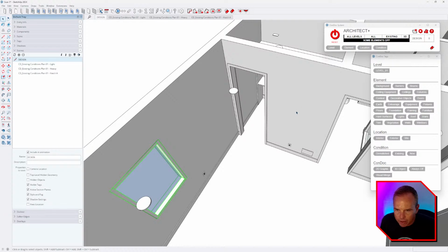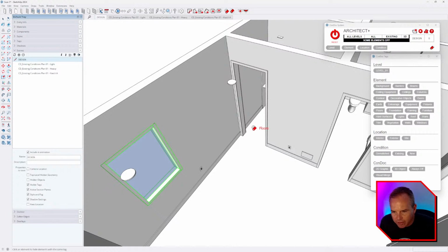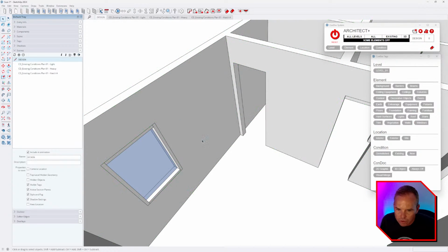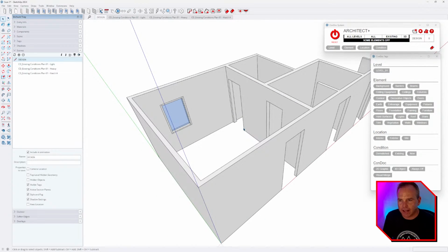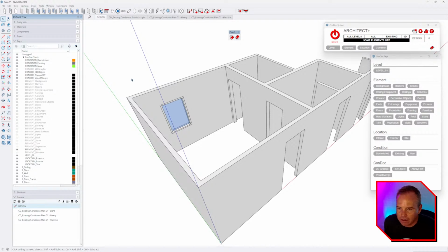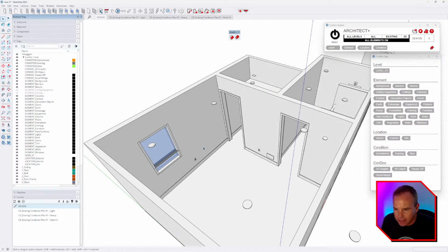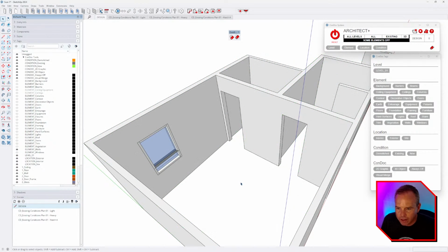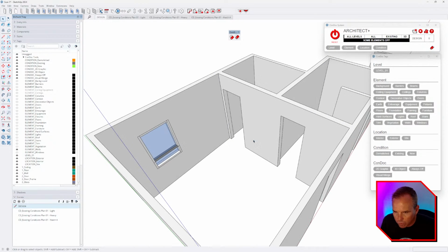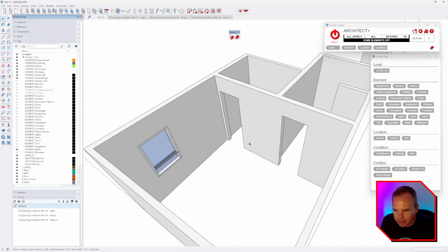All right, then the other thing I want to do is, you can either freeze the trim, or you could isolate the walls. So you can see how these express tools keep you out of the tags dialog, and same with the Condoc system. You can always get back to where you want to be and just say, you know what, I'm working on my doors and my windows. I'm just going to isolate the walls and the windows for now.